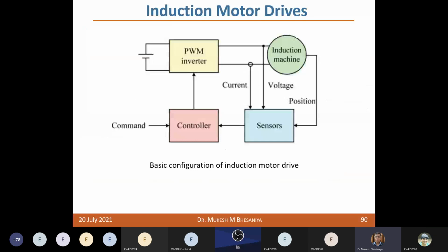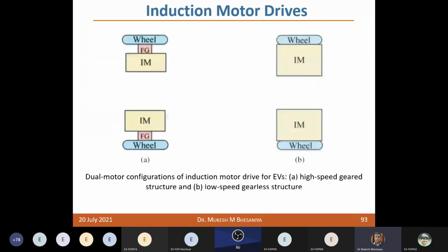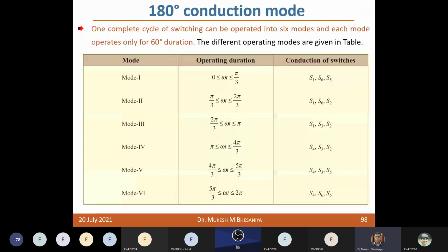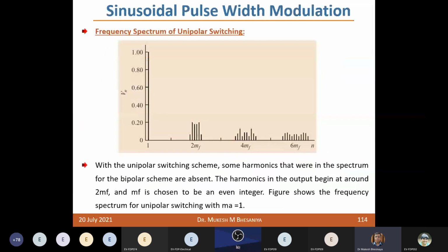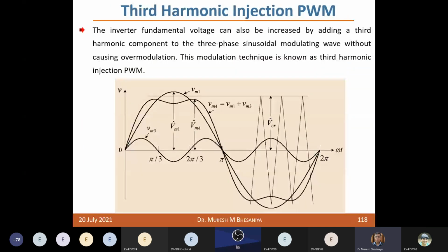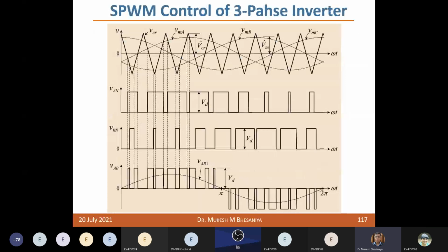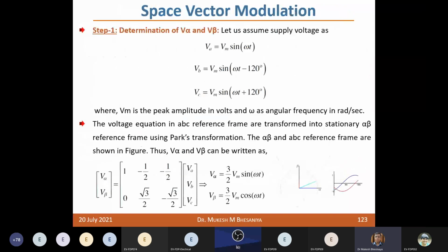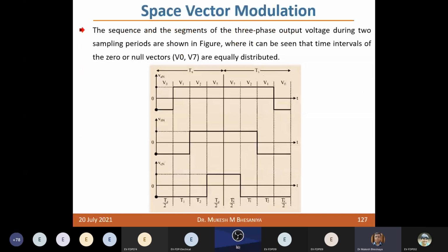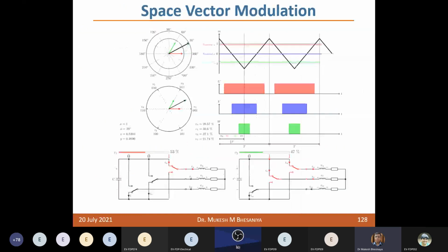Then another aspect is the induction motor drive. Due to lack of time, I'm not going into all these converter control and configurations, but you can refer to this. Various control methods like SPWM, third harmonic injection, or space vector modulation are used for the control of these inverters.